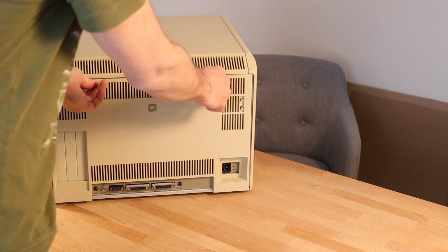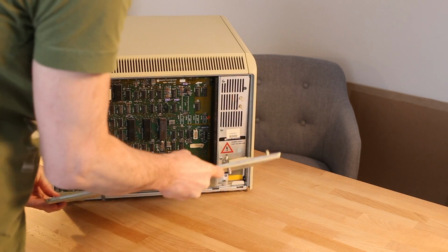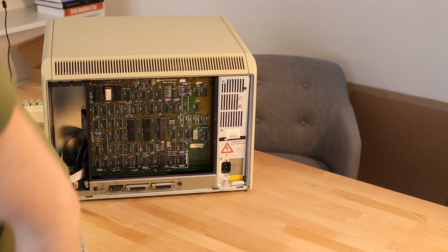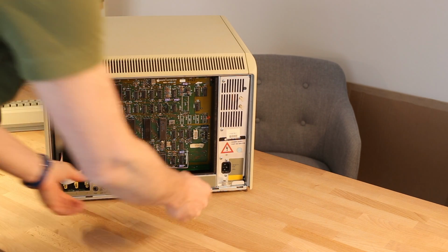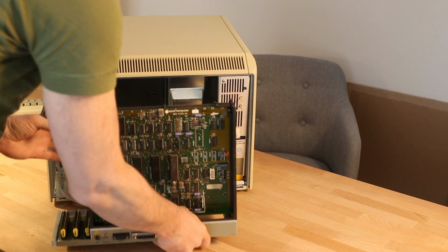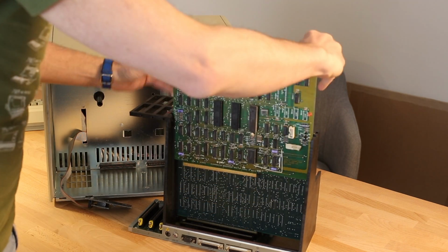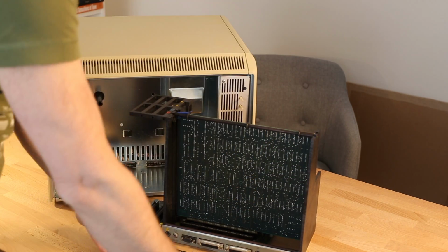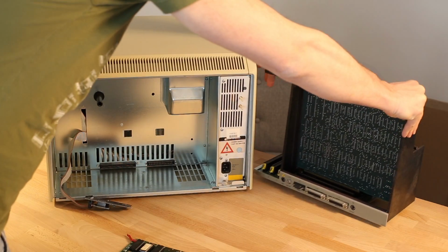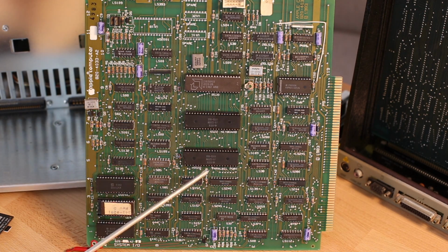Shift register is a generic method for transforming parallel data to serial and vice versa. It can be used for serial communication, to drive LED displays, and for many other applications. The shift register which Apple Lisa uses for sound generation is implemented in the MOS 6522 Versatile Interface Adapter, or VIA chip. Lisa has two of these chips, one mainly responsible for disk operations and the other mainly responsible for keyboard and mouse input-output. The latter is also used for sound.